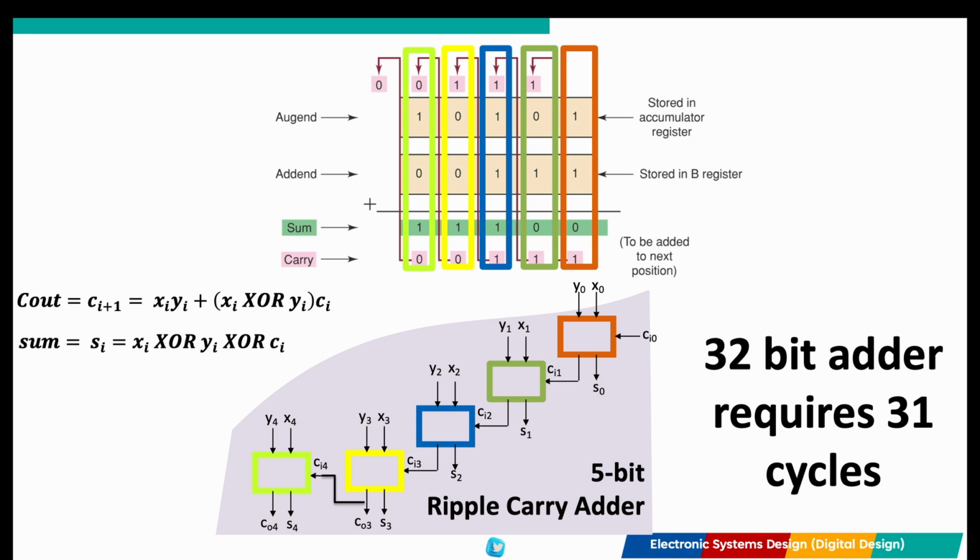The carry look-ahead adder works by defining 2 new signals for every bit position. The propagate signal is high if the current stage will pass a carry from the previous stage to the next. For example, logic A exclusive or B. By using these propagate and generate signals, we can calculate the carry for the 4th, 8th, or even 16th bit almost instantly, without waiting for the bits in between. We are trading area for speed by making more gates and less delay.